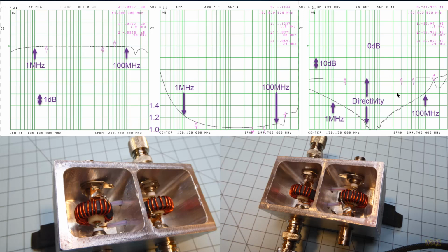And when I put 200 watts of power into the circuit, it produced a core temperature rise, not in the current transformer, but in the voltage transformer. These little terminators are shown to be the coupled ports, and this is where I put the power in. The transformer that samples voltage was at 53 degrees Celsius. At 100 watts, it was at 21 degrees Celsius temperature rise. And that's with a 1-to-1 SWR, of course.